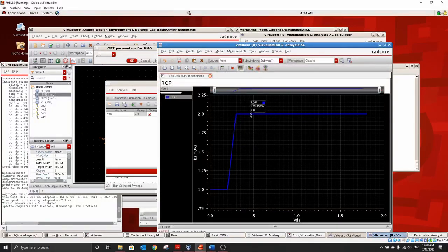Clearly you could see that this is the region of operation, and region 2 basically denotes that we are in the saturation regime, and region 1 basically denotes that we are in the linear region. And obviously you know what region 0 would mean over here. I'll leave that to you. In this case, the way that we are going to measure the minimum voltage is to look for this 2 that is ending here towards the left.